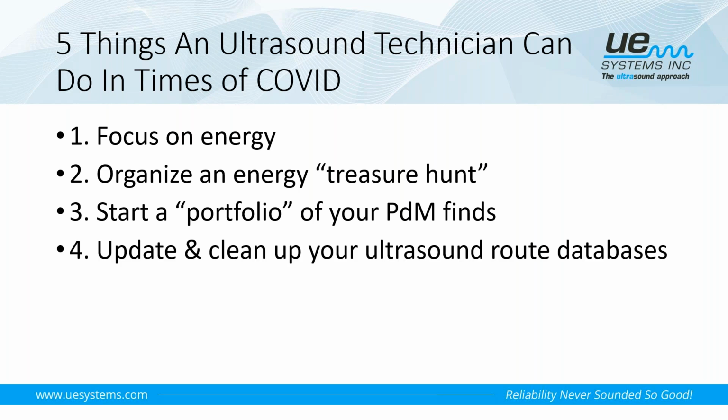Number four would be to update and clean up your ultrasound routes and databases. I know some of you out there have been running mechanical routes with ultrasound for many years. And you may just have some data that is really not useful to you anymore. So you can clean that database up. And if you're using DMS5, what we would recommend there would be to export that data out to Excel. That way it's not permanently deleted, but you still have a record of all those previous readings.